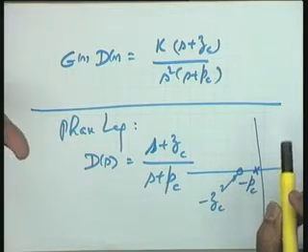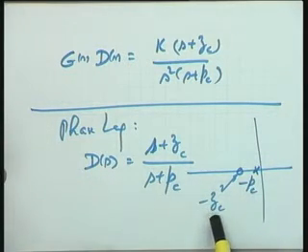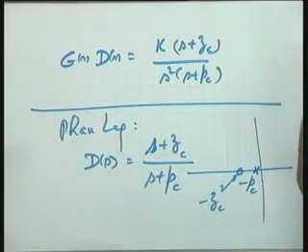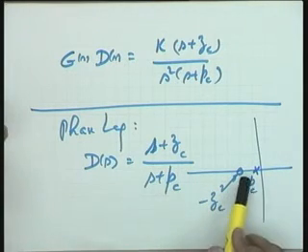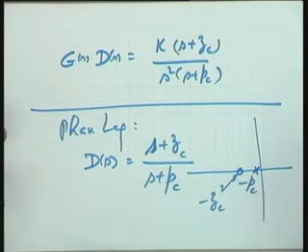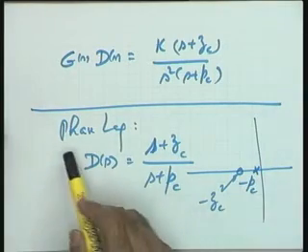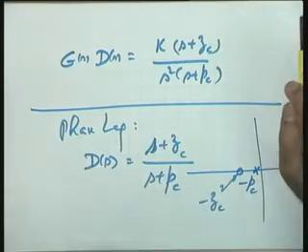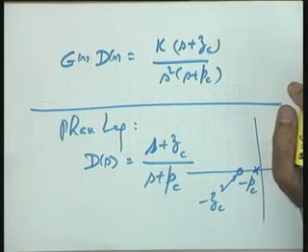At the most you can say that you will suitably control the values of Zc and Pc so that the transient performance is not deteriorated, but it will definitely not improve at least. That is why I said that I will place a zero close by so that the negative effect of the pole on the transient performance of the system is compensated. So you must set these requirements in your mind. You have to take a decision as to whether you want to go for a phase lag compensator or a phase lead compensator. I will say that a phase lag compensator is possible if and only if your uncompensated system